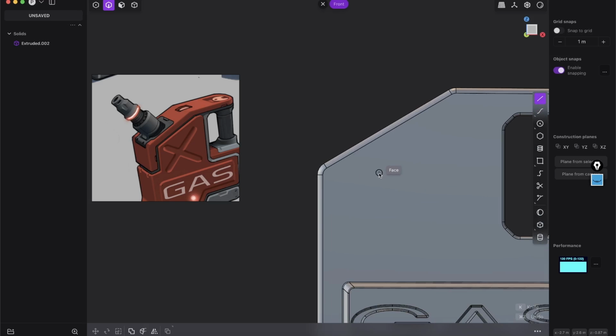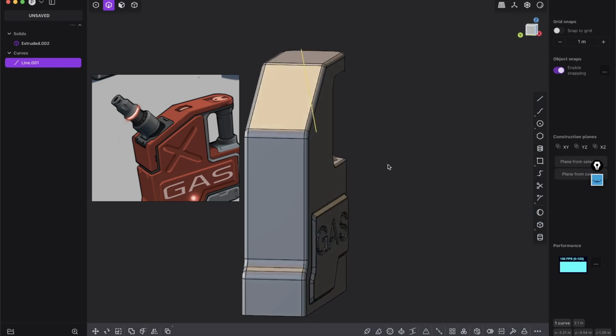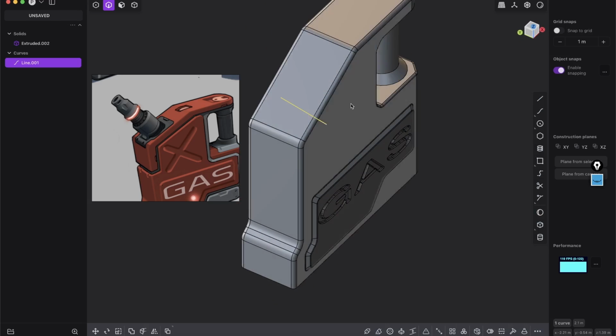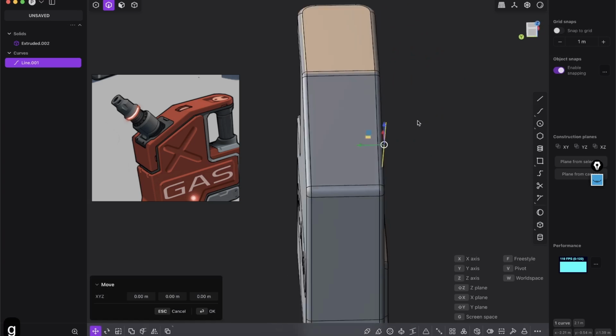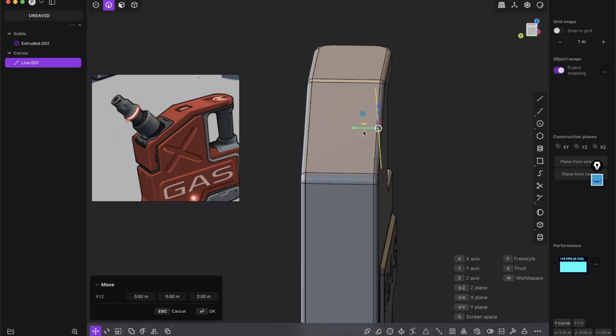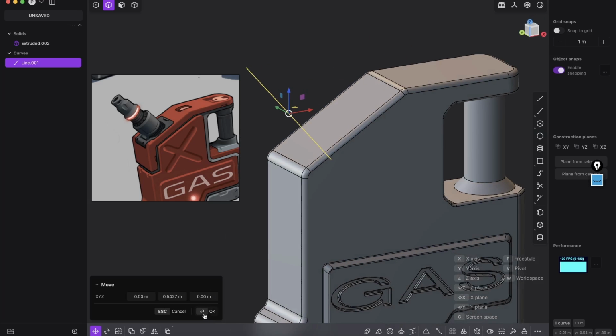And if you just click here on the face and drag that out, to something like that, right? And we want to bring it in the middle because now it's snapped to the face. So press G. So you have this pivot and just drag that on the Y-axis and press Control click while you drag with your mouse. And then you can snap it to those center points. You see, now it's in the middle.